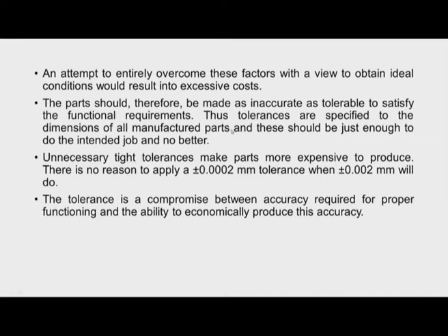Thus tolerances are specified to the dimensions of all manufactured parts, and these should be just enough to do the intended job. Unnecessary tight tolerances should not be specified. Say for example plus or minus 0.0002 mm should not be specified when plus or minus 0.002 mm will satisfy the need.